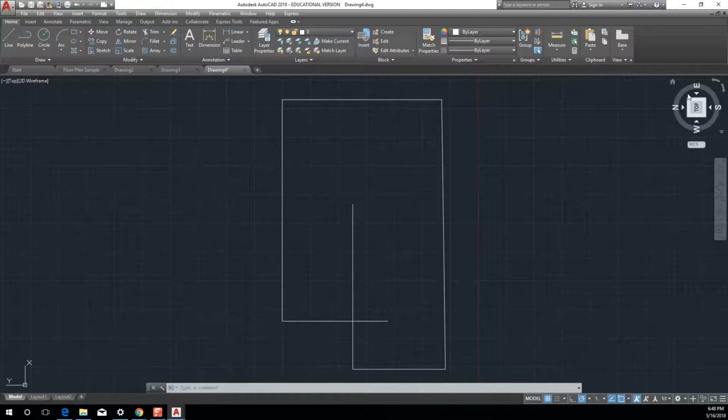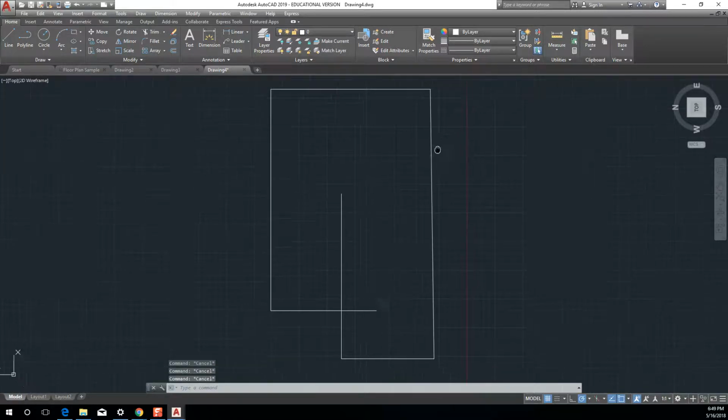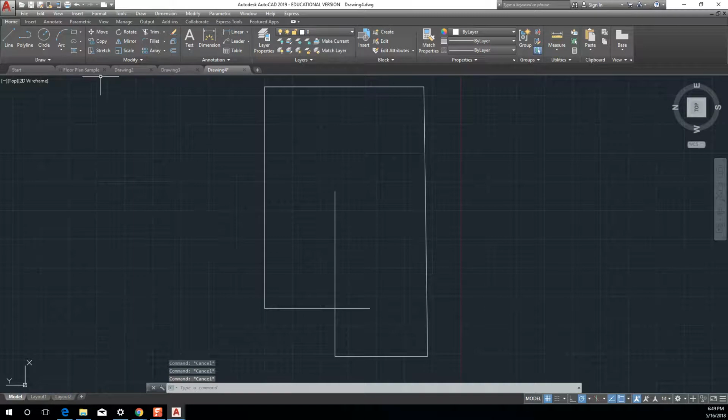It looks flat in this view. My line looks flat when I'm looking at it like this, but when I change to this view and look at it from the side, it's definitely not flat. It's non-coplanar, right? That's when I realized that using this view cube puts you in a top view. You're viewing this in plan view, but in a perspective view at the same time. And so AutoCAD at times would snap to different planes, a foot away, 2 feet away, and we'd get these really crazy lines going on. So when I looked at her model in a different view, all of her lines were just all crazy. That was a tough one to figure out.